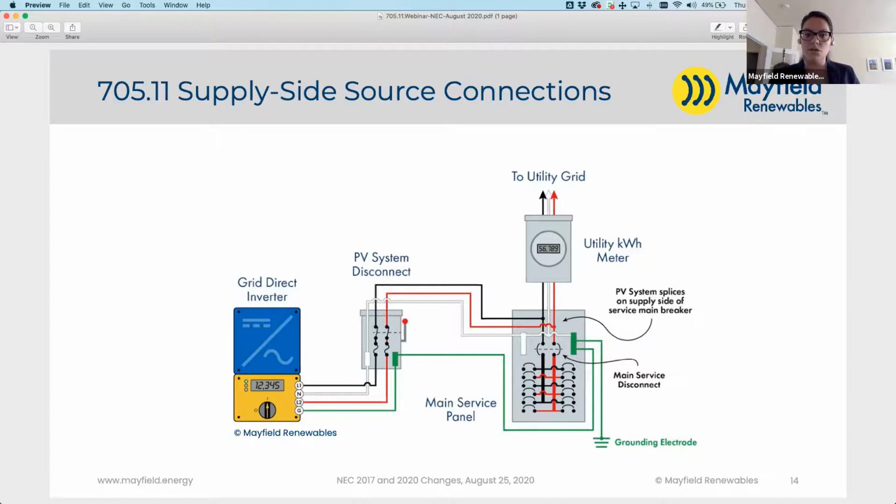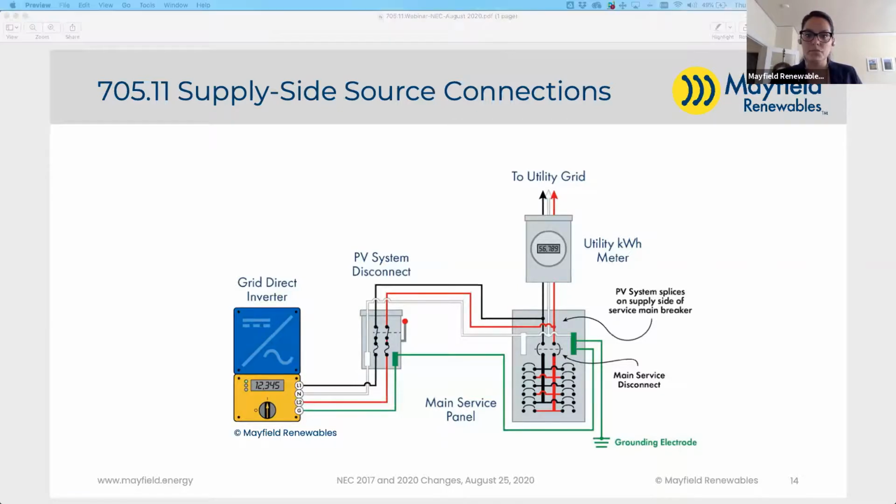So this next question is, what is the NEC reference for OCPD requirements in DC to DC converter source circuits? Yeah, I think 690.9 covers that. 690.9(A) basically just says that PV system DC circuits shall be protected against overcurrent.